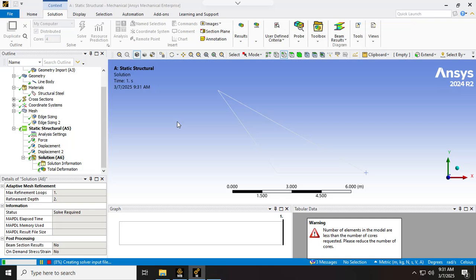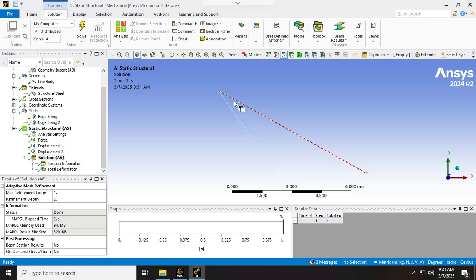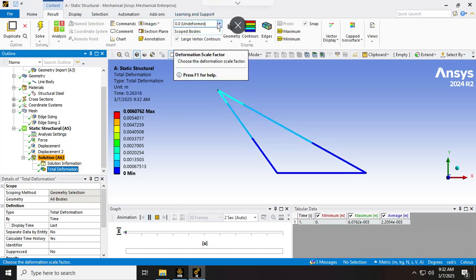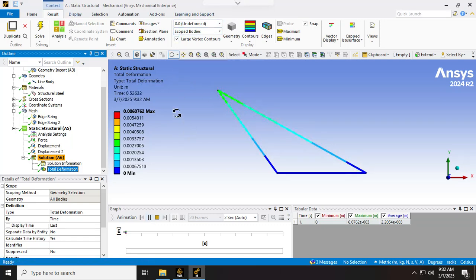The difference is gonna be this: if you have beam, the supports here, the way the elements are connected to each other, you could have them welded here, right? But for truss or link elements, this point cannot be welded. It's gonna be just a pivot. So that's the difference. Now let's look at our displacement too, but this is again right now the true value.